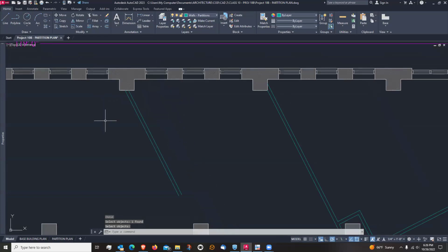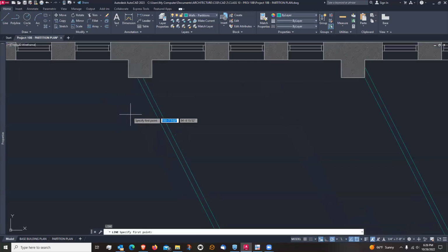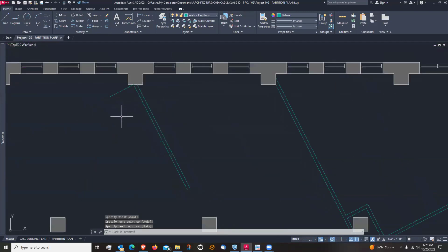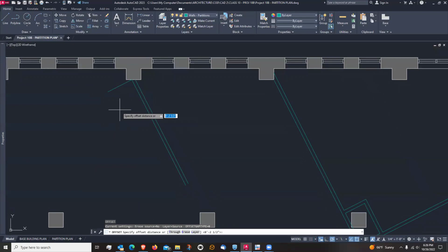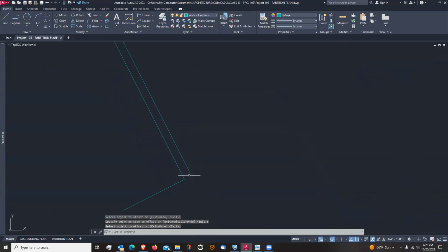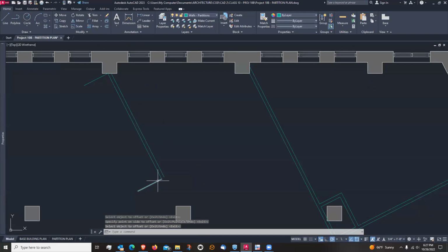So, all right, now I have to O-track over 16.1, but O-track doesn't like using these wonky angles here. So what do I do? Well, I'm going to draw a little guideline here, and it's going to be perpendicular to this wall. So it's going to come out just like that. And then I will just offset it 16 foot 1 inch. And wow, I drew that almost perfectly, didn't I? And that is going to be the outside face of our partition.